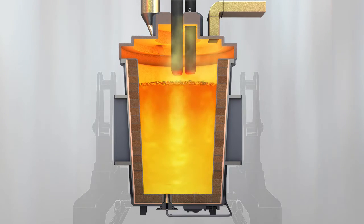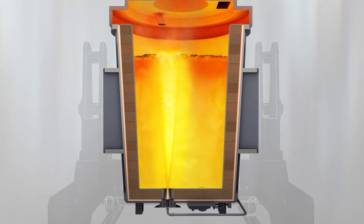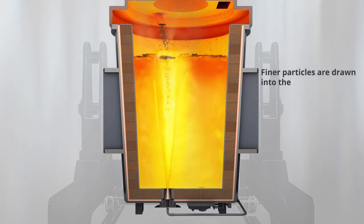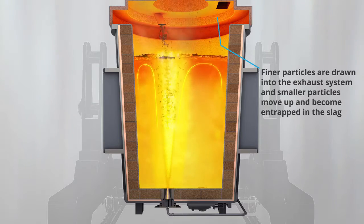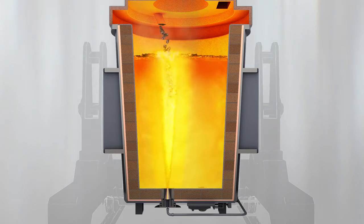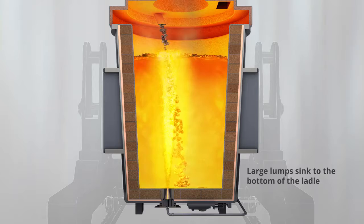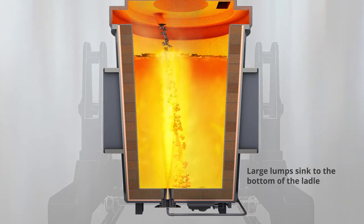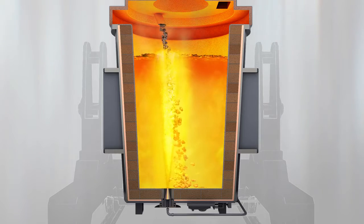It is critical to ensure that the state of deoxidation and the temperature of the ladle are correct. During delivery into the ladle, the size of the particles or lumps is of key importance. Too small or fine, and there is a danger of unwelcome losses via the extraction system, or they become entrapped in the slag. If the lumps are too large, they will sink too deeply into the ladle and their subsequent dissolution may be adversely affected. The velocity of the particles being delivered through the chute is also therefore very important.